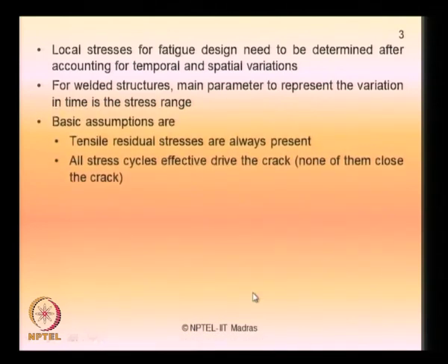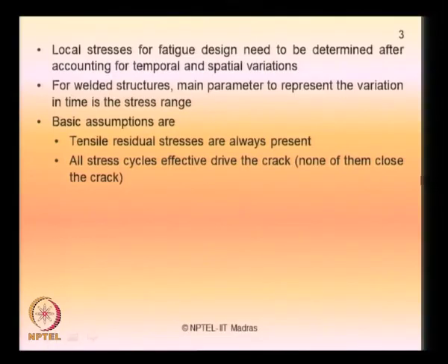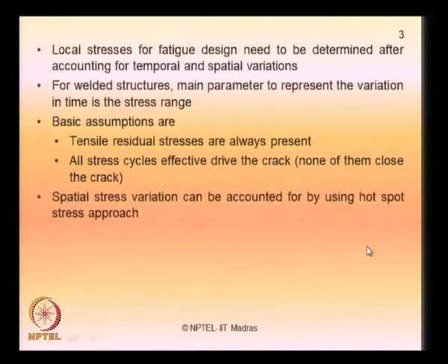The basic assumptions actually made in such analysis are the following: the tensile residual stresses are always present, and all stress cycles are effective in driving the crack; none of them closes the crack. The spatial stress variation can be accounted for by using the hotspot stress approach.